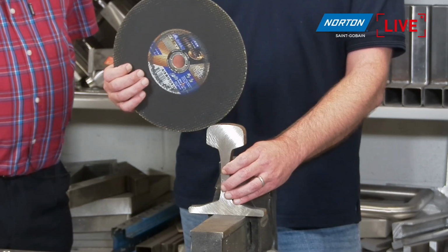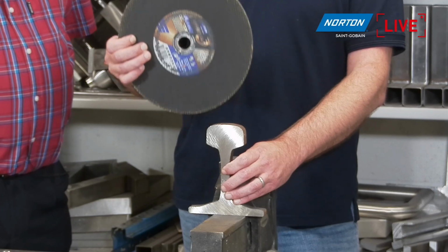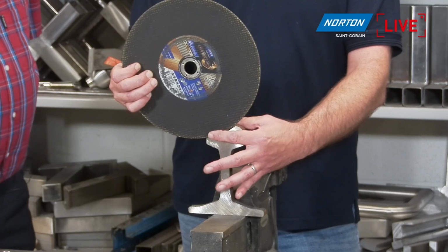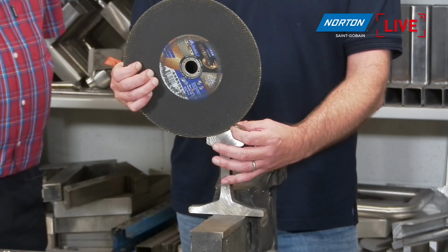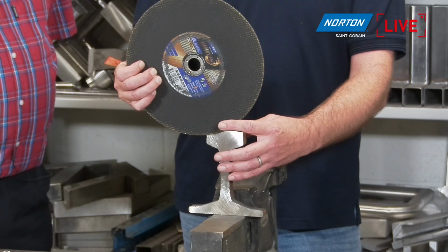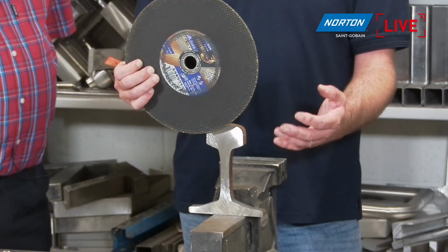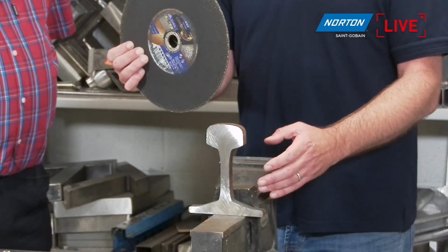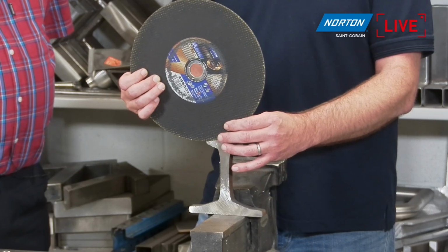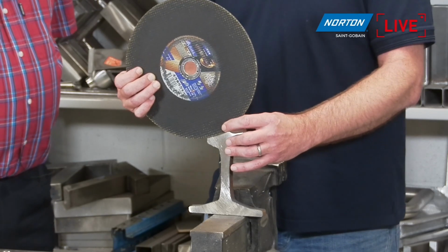There's actually a couple of reasons why we do this. If we stay in the one area, we end up going into the material and we have what we call a very large arc of contact. There's a lot of material touching the blade, effectively forcing a huge gripping area, producing a great deal of heat, and that's an enemy of the blade too.